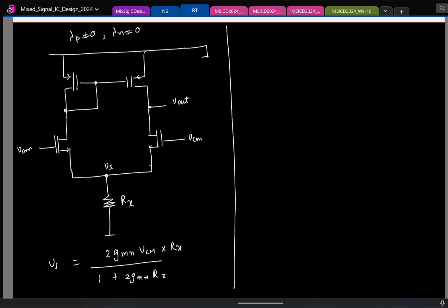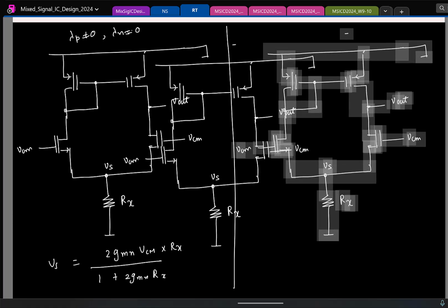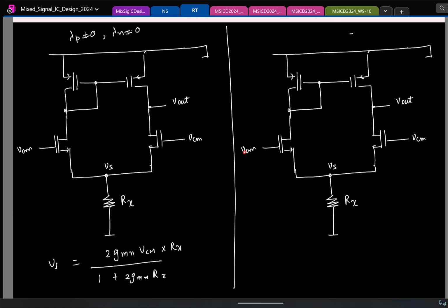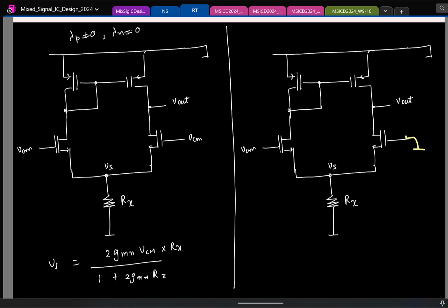See, again I can consider the setup like this. I have a linear circuit, a small signal linear circuit. I have 2 excitations. So how can I solve for this? A linear circuit with 2 inputs. What do I do? Let's use superposition. Let's say this is not there. Fine, maybe I'll use a different color. Let's say this is grounded. So what is the looking-in resistance here?